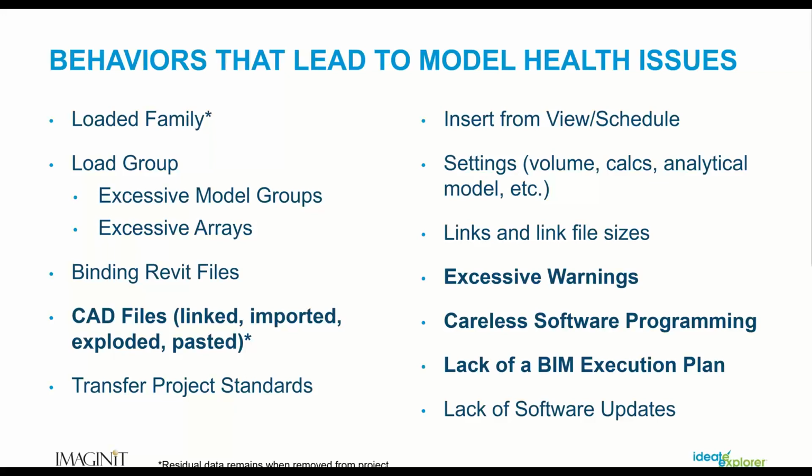Notice how that CAD file is bolded out, and a couple of other ones as well, but think about bringing in a CAD file, whether you link it or import it. There are a lot of crazy things that happen graphically when you bring in those CAD files. Be careful, especially when you've imported a CAD file and then somebody's exploded it. Oh my goodness, what kind of overhead you're going to have on that.